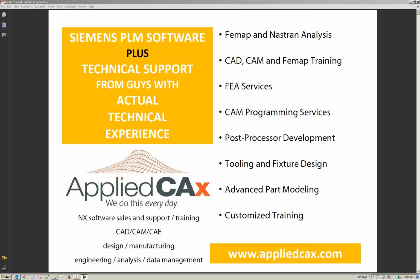Today I'll be demonstrating how to bring in STEP models and set them up for manufacturing. This particular STEP model has PMI, or 3D dimensioning, as we do support that, and we'll be bringing it into an inch template to convert it from metric, and then we'll be orienting the model normal to how it will sit in the machine.